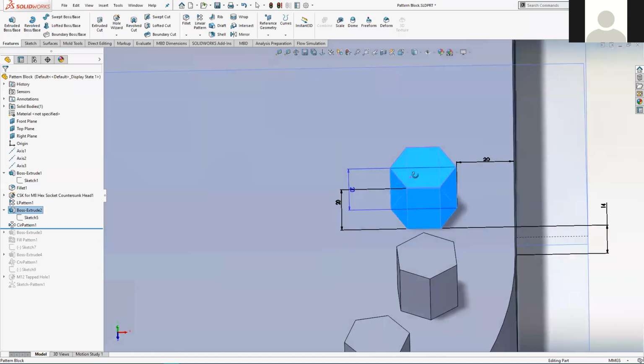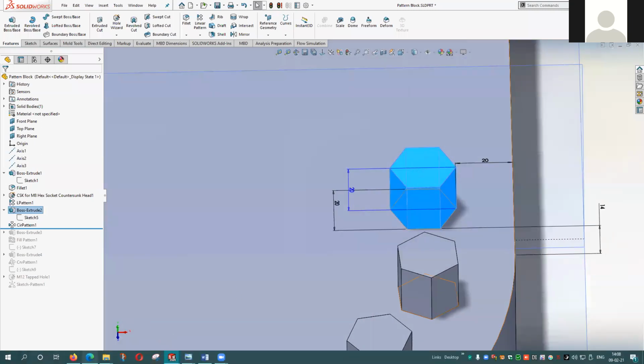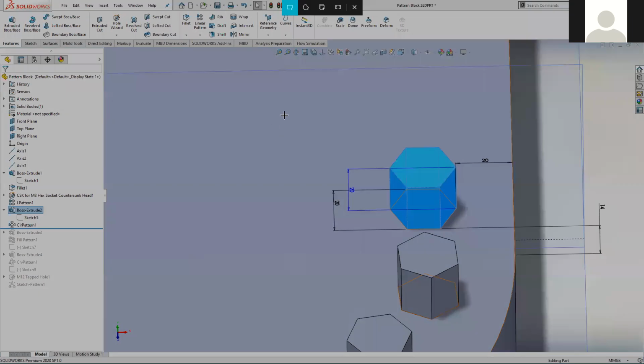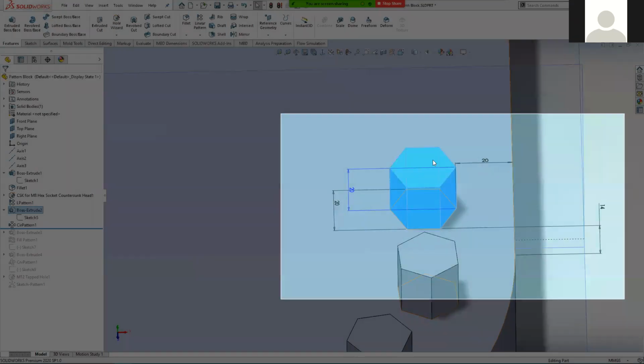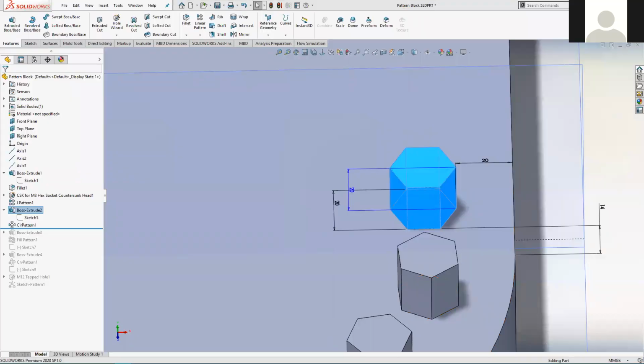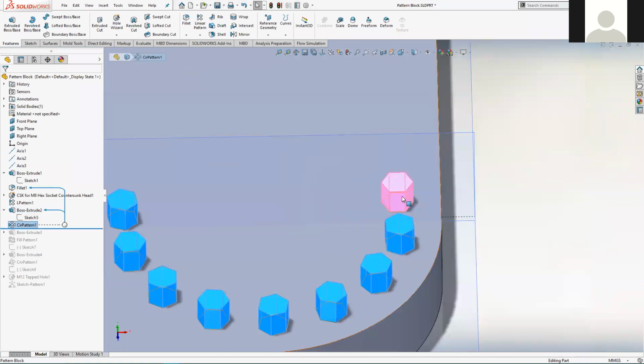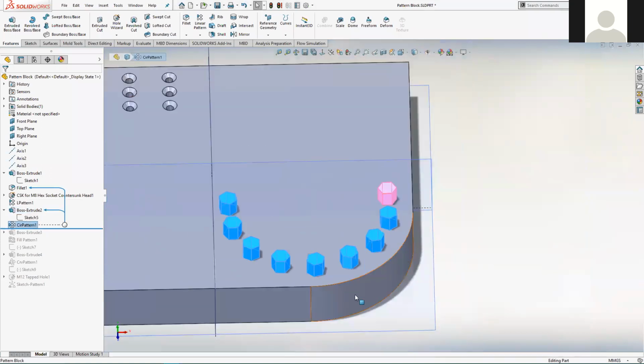Those are the dimensions of it, which I might just take a little copy of so that I can have that off screen as a reference. I'll take a quick snip of that, use that as a reference, and we'll create that ourselves. And then the circular pattern feature gets used with that curve as a reference direction, or that supplies the center axis of our pattern.